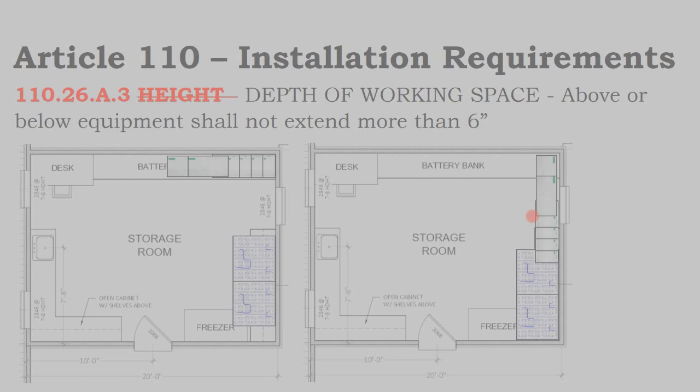And so you can't have one piece of equipment that sticks far out from the wall and another piece of equipment that's inset into the wall stacked on top of each other. Those technically would be different zones. It would violate it, you would need 2 different working spaces. So to put them on top of each other, you'd have to have a 6.5-foot section and then another 6.5-foot section, although that would be very impractical for the most part.